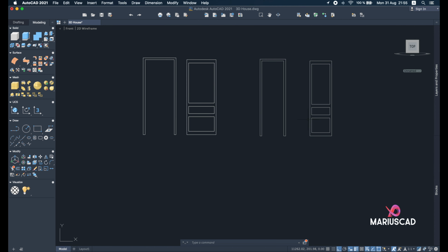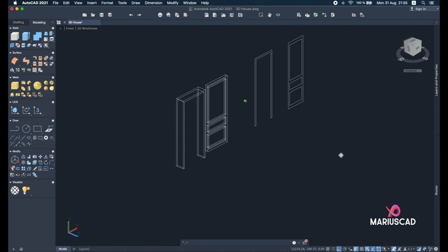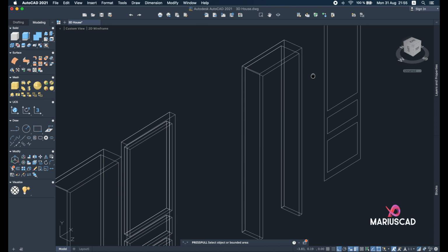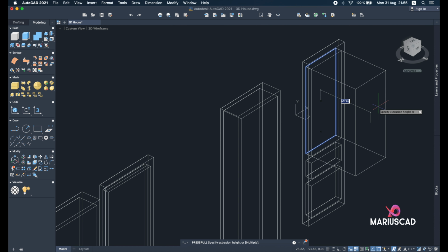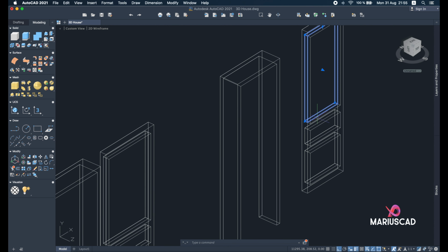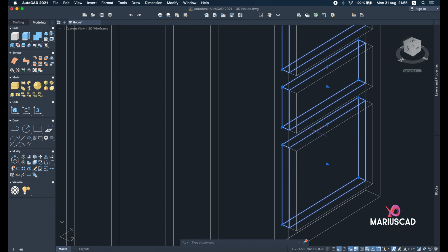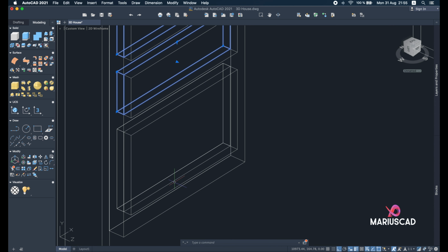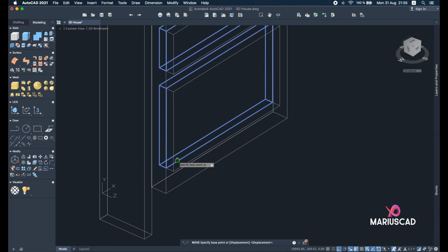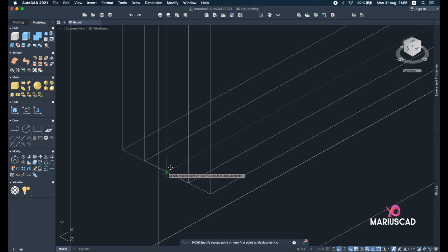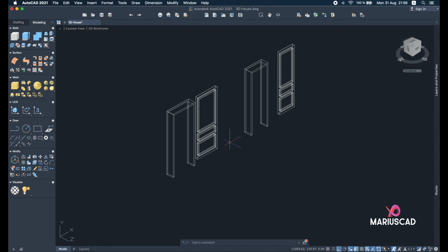Good. Another important fact, it will be now again to use the press pull command for the other door. So as I said to you before, 25, the thickness of the wall, 8, and for each of these 4, 4, and 4. Now let's move them all, the interior, I mean, just the interior. These 3 parts. So move and put them in the middle. Yes, perfect. Now let's put these doors where they should be.